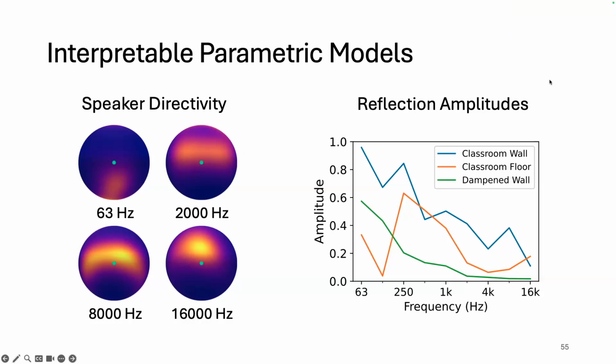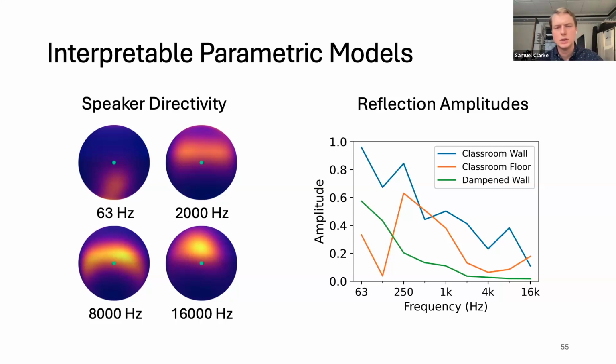Okay, yes. So on page 56, I think the reflection is only modeled in the magnitude response. The magnitude response. Okay. So you apply the minimum phase reconstruction to obtain the impulse response in the time domain. So how accurate is the waveform itself with respect to the recorded original data?